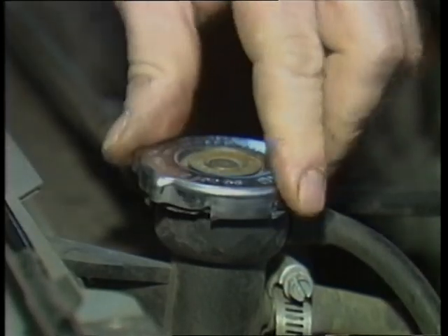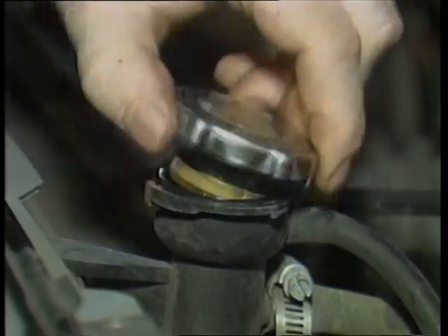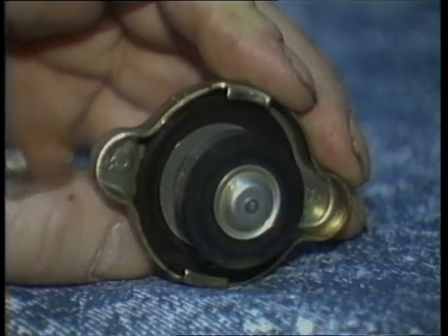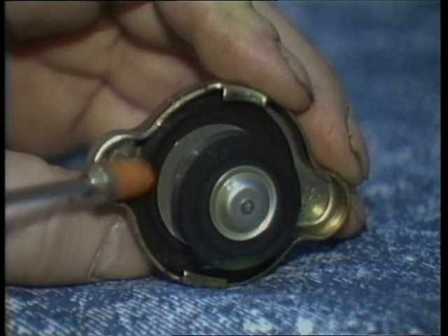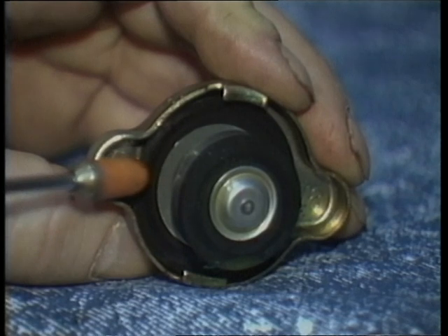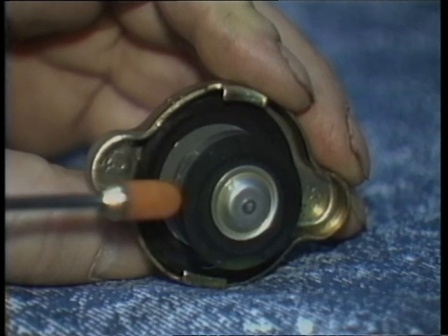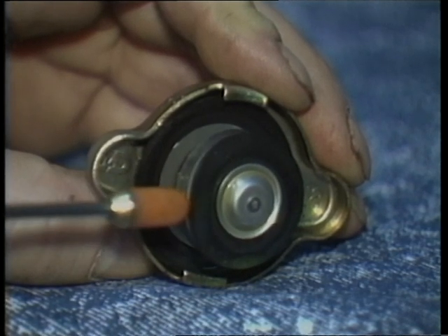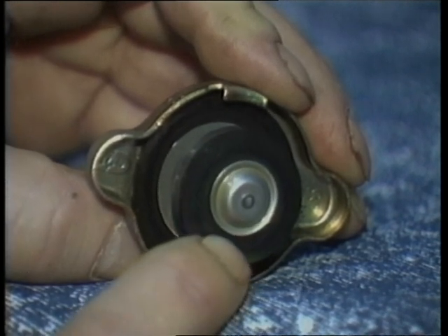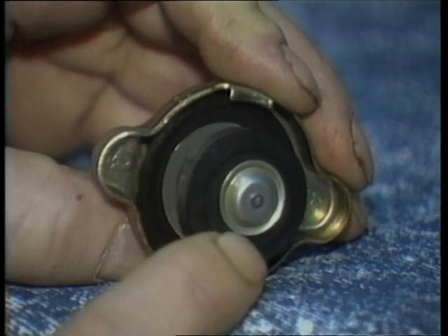A pressure cap mounts on the radiator neck or on a reservoir tank. By pushing down and turning, you can remove or install the cap. One rubber seal on the radiator cap contacts the top of the radiator neck to allow overflow action. The smaller seal is a pressure seal. A vent valve allows the entry of coolant from the coolant reservoir.